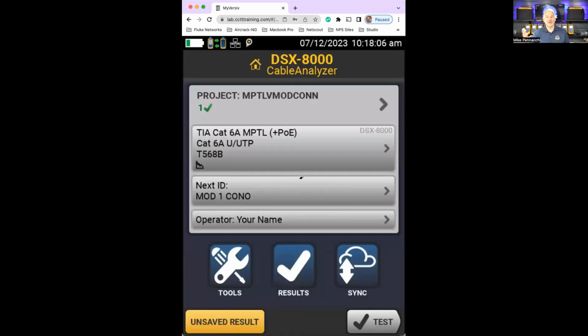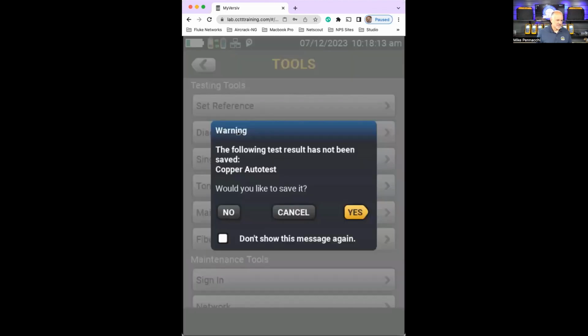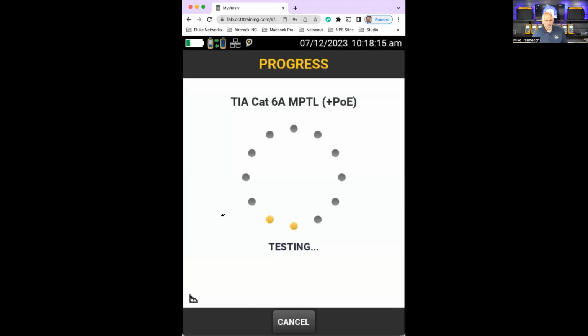Now, you're saying, okay, Mike, let's see the diagnostics on that. So I'm going to come into Tools. I'm going to go to Diagnostics. Say, no, we're not going to save that. So now this time we're going to run the MPTL Cat6A test, but we're doing our diagnostics along with it so that we can see what our near-end crosstalk looks like at each of the different points along that link.